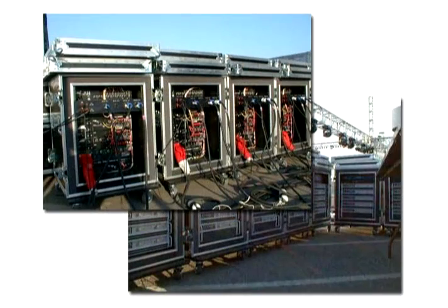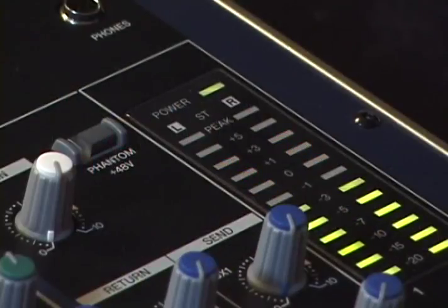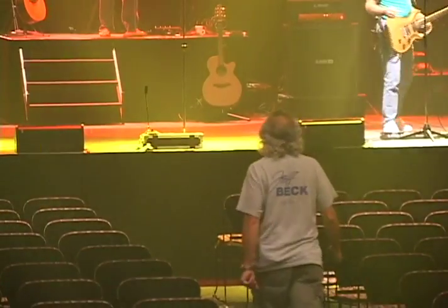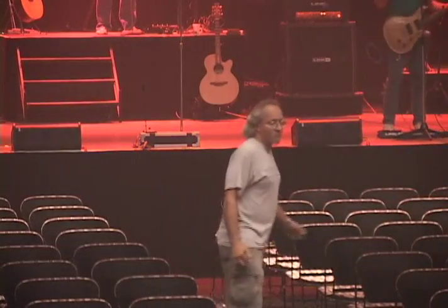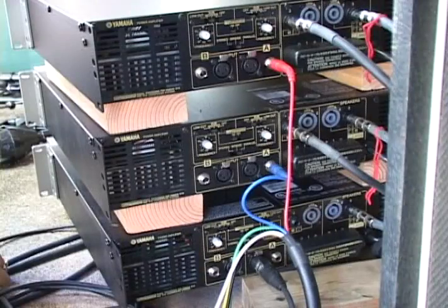Large touring rigs encompass a range of effects from compression and limiting to EQ that would be applied to the mix as a whole. This has a dual function, both as a safeguard against dangerous level spikes that could damage loudspeakers and as a fine-tuning device to tailor a mix for a particular room or setting. Effects for this purpose will be connected in line between your mixer's output and your amplifier's input.